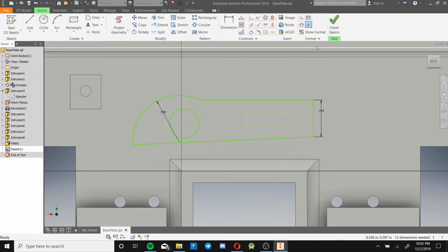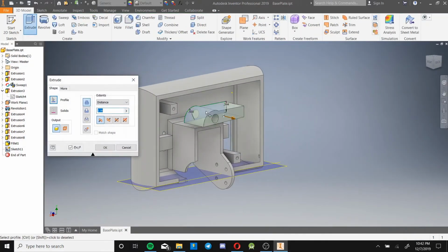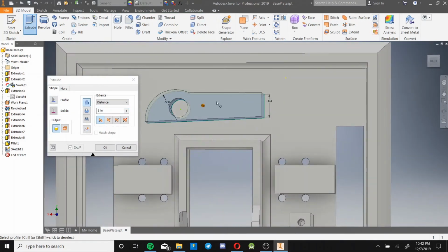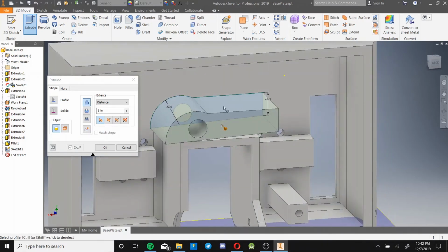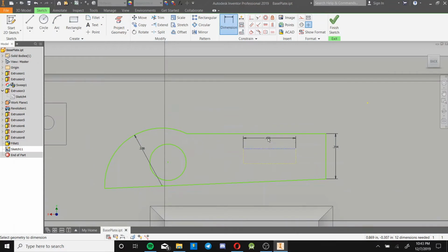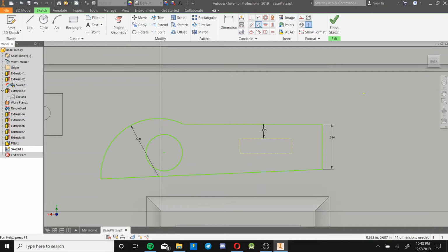And if I were to extrude this now, okay, notice how it saw this solid line as a border, but it didn't see these construction lines. Like I can't select it, right? I could select this. I could deselect this by holding control. I could deselect this by holding control, but I cannot select the construction lines. That's what they're there for. They're just for reference. So with those construction lines, I can then dimension based off of those, okay? Or I can do constraints based off of those. They're really useful. I'll get into them and more advanced concepts as we build the robot.